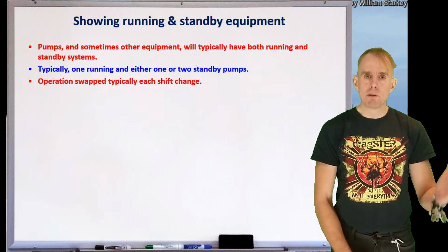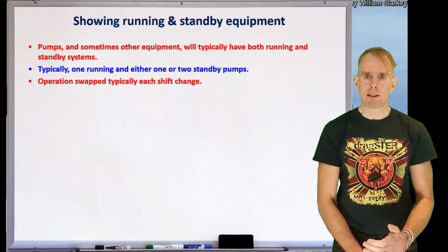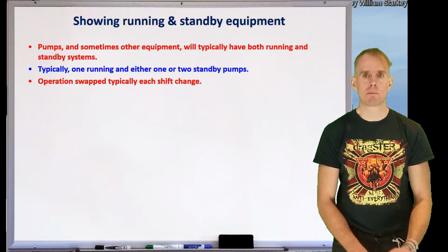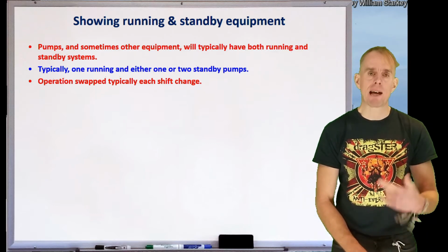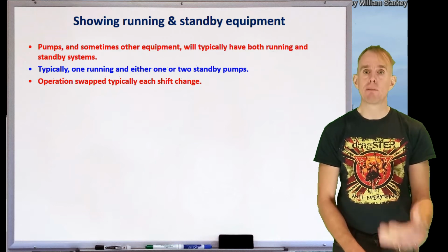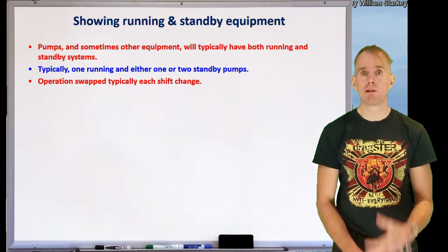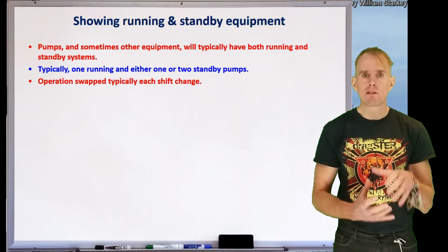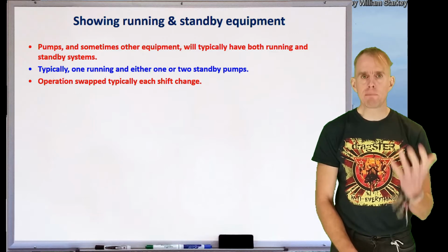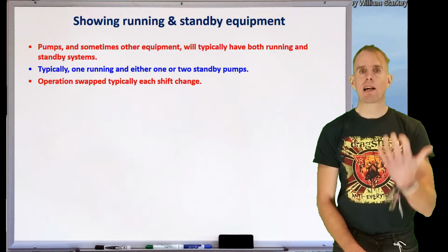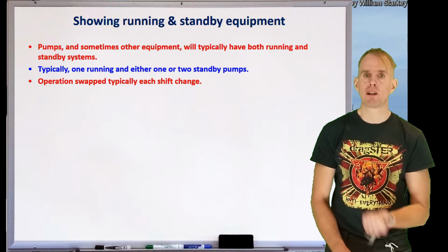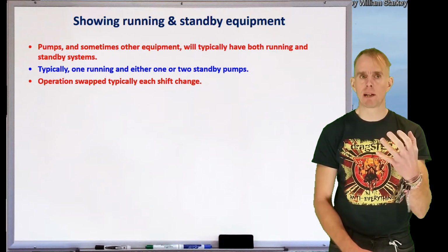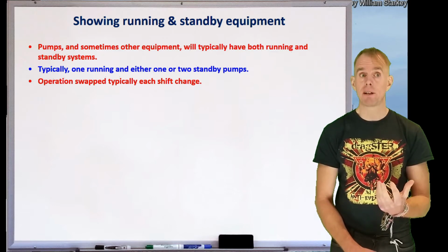If you've got a pump removing liquid from a vessel and it fails, you don't want to shut your process down. Pumps are mechanical items of equipment. They're subject to wear. Their efficiency can go down as they wear. They're also typically motor driven, and the brushes on motors can also wear and may need replacing. And so you never have a single pump in isolation. You have a pump that is doing the service, and then standby pumps that are ready to automatically turn on if another pump fails. And so typically you'll have one pump running and maybe one or two pumps on standby.